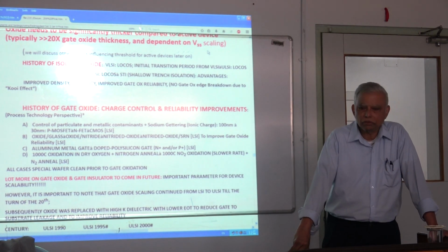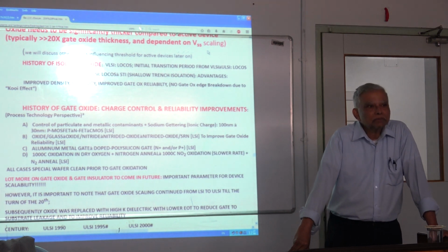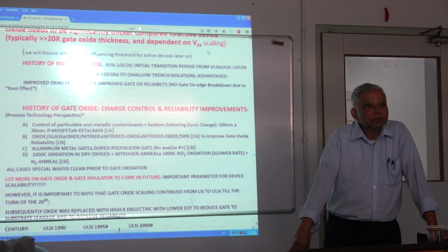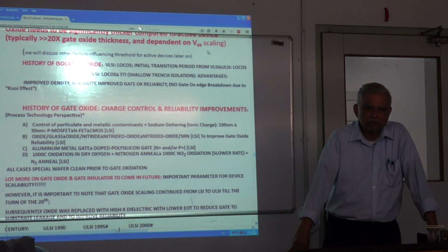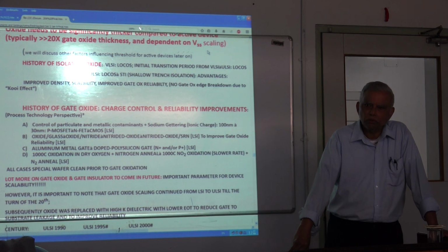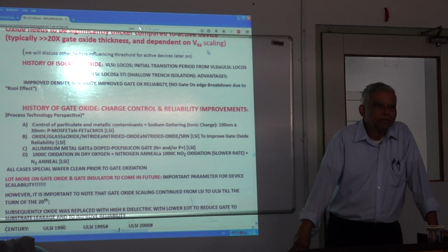That's another story I'll tell you sometimes. But the field effect transistor had about 40 angstroms EOT, effective oxide thickness, not exactly oxide, it's a nitride oxide. But that's about the thinnest I went before we had to go for high gate-dielectric.